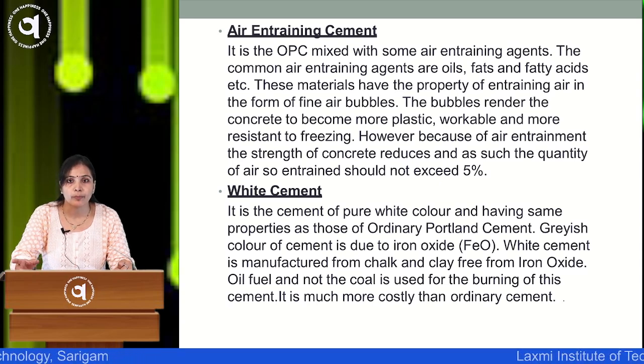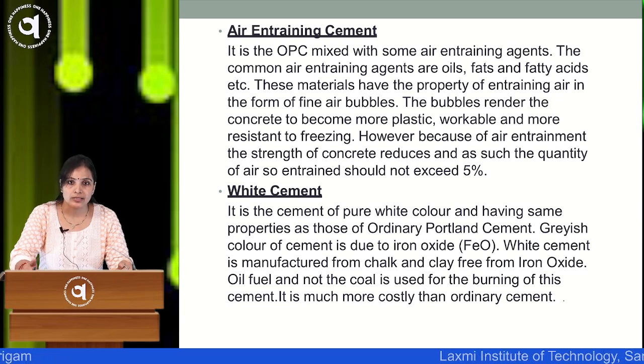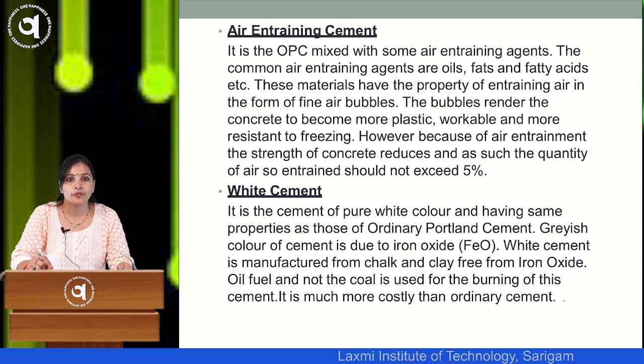These materials have the property of entraining air in the form of air bubbles. These bubbles render the concrete more plastic, workable and more resistant to freezing. However, because of air entrainment, the strength of concrete reduces, and thus the quantity of air so entrapped should not exceed 5%. So, the limitation is there for the air entrained.